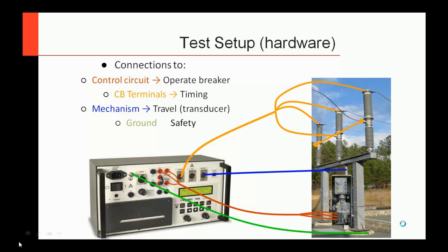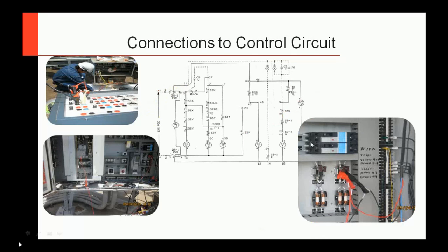So, connection to the control circuit. I always recommend reading the print. Some people say there are some common connections such as 5, 7, and 9, but I never rely on those. I've seen stuff written in the cabinet and everything. I always verify the print. I always ask for a print because you don't know who wired or who did what. As long as you refer to the prints, hopefully you'll have the correct connections, as long as no one's changed anything and not mentioned it on the prints.